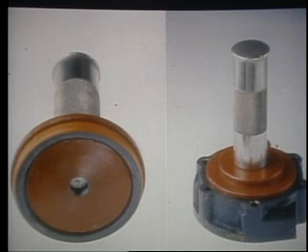To prevent damaging the seal, use an installation tool that has a larger outside diameter than the seal and bottoms against the rear face of the bearing cover. To protect the system, be sure the seal driver is clean and free of nicks or burrs.